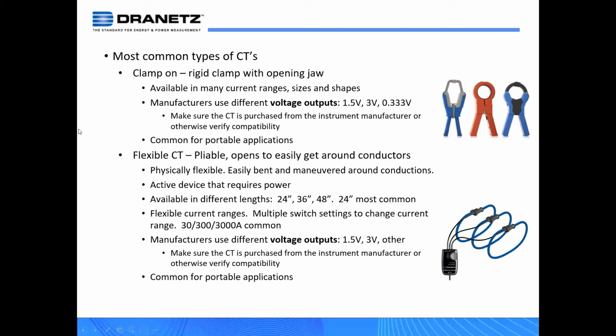You have different types of CTs, clamp-ons. Again, we're kind of using the term CT, but in this case, it's actually a current probe. But again, you have the different voltage outputs. Again, 333 is the most common. The very popular flexible CTs.